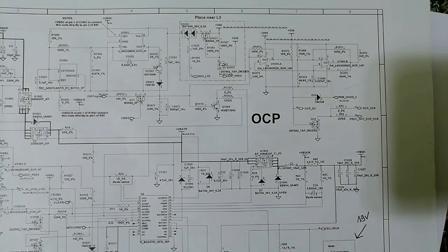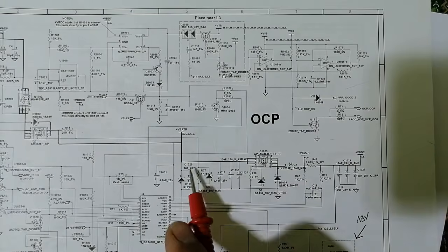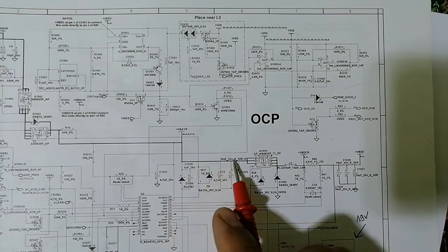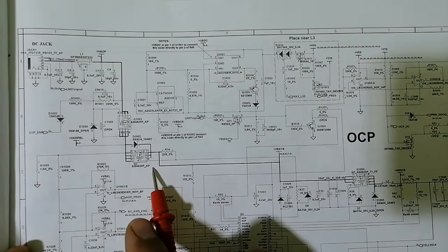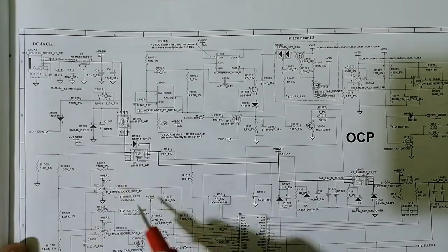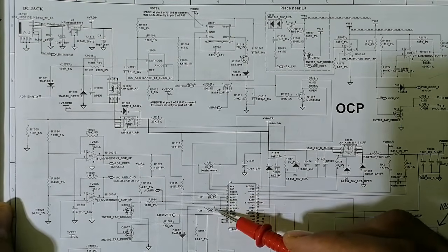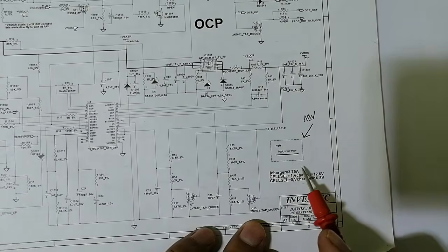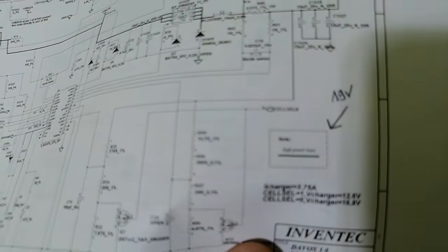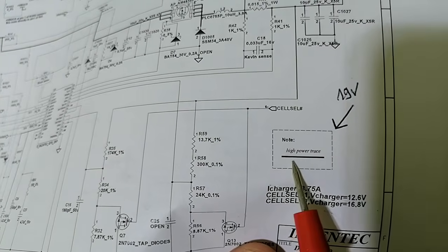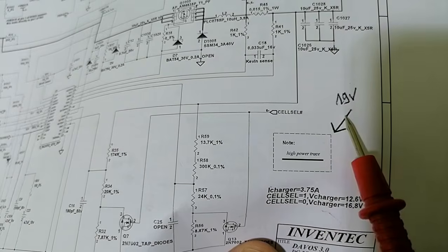So also in the circuit diagram, you will find the same working principle, as you can see. Do you see over here? This is a bolded line. So this bolded line basically means we have a high voltage over here. And those lines, as you can see, mean just a signal, a low voltage. So if you pay attention here, guys, we have a note in the schematic. Do you see? This line means a high power trace, 19 volts.